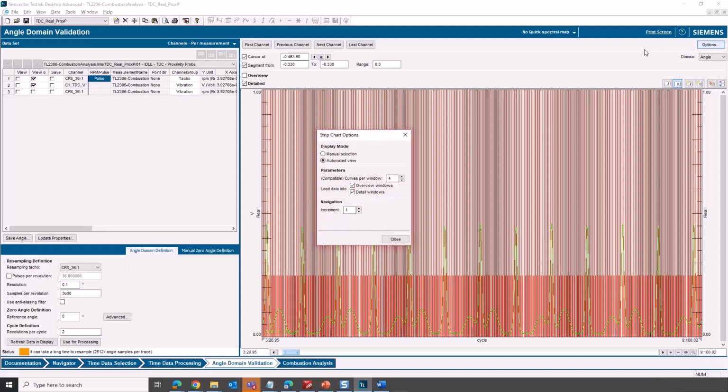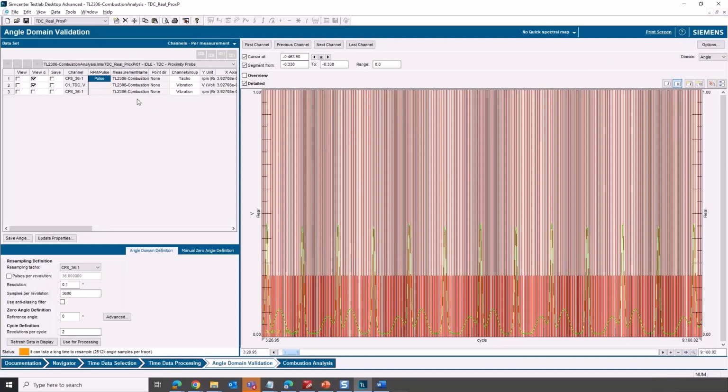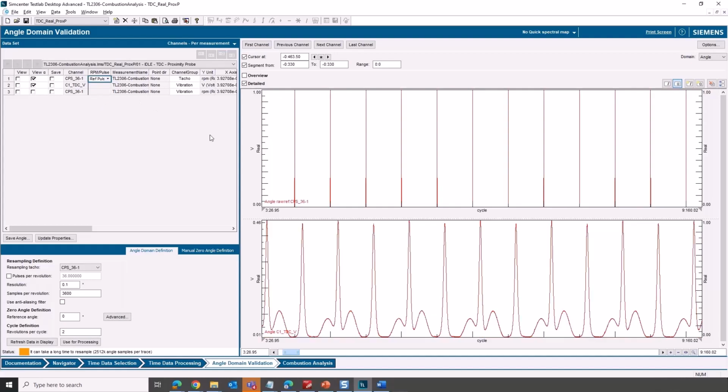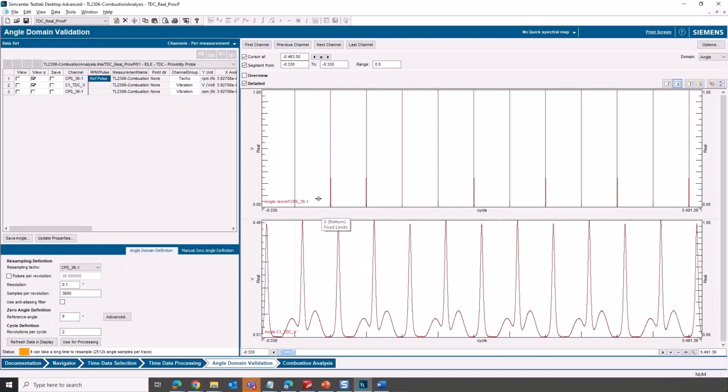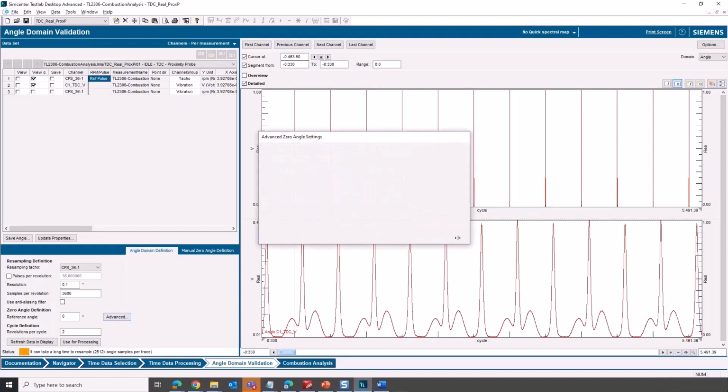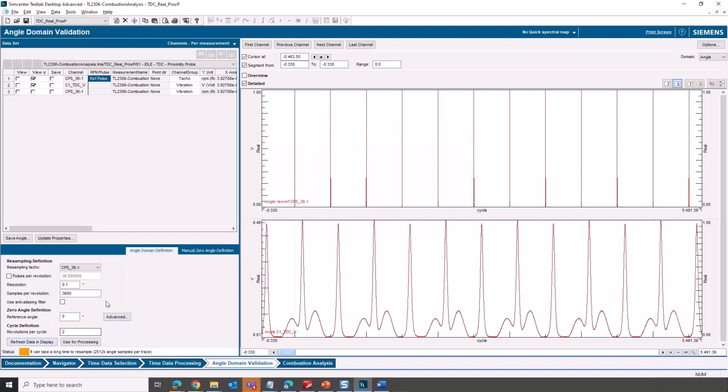I didn't know that you could flip that little thing from RPM to pulse to see the actual pulses. That's kind of cool. Yeah, it is indeed cool, because that is really useful information and it is coming from the tacho measurements that we were talking about. The reference pulse is the single pulse per rev and the other one was the higher pulse per rev. And that's why the one looked denser than the other, huh? That's correct. Yes.